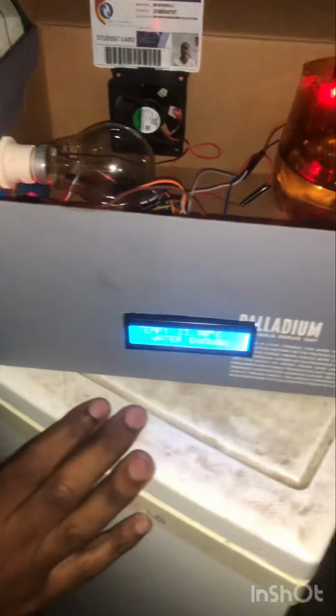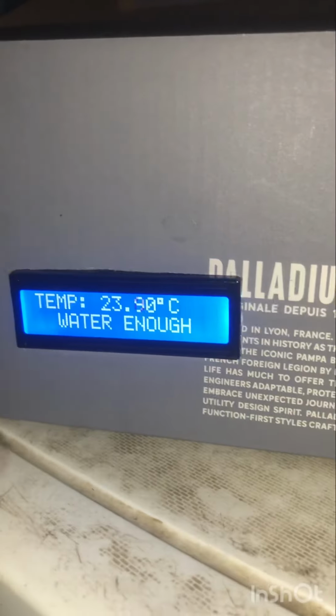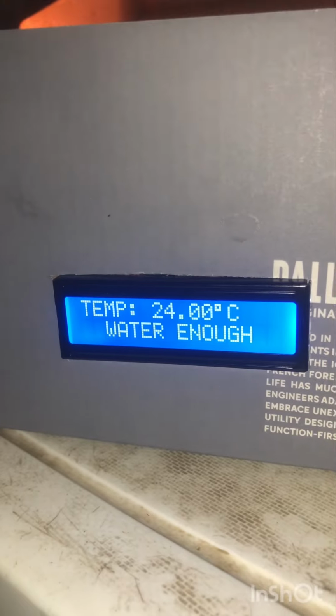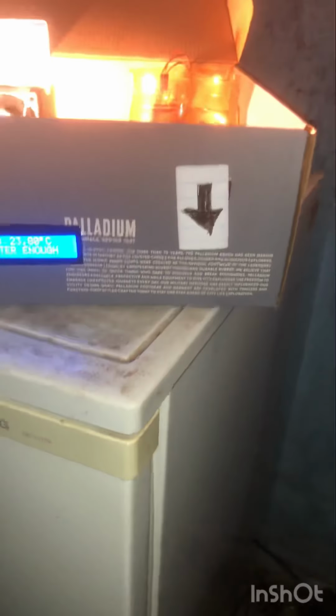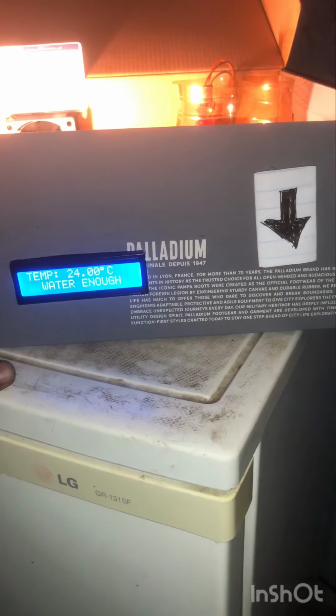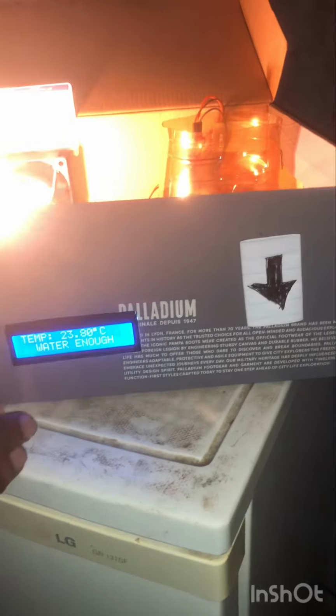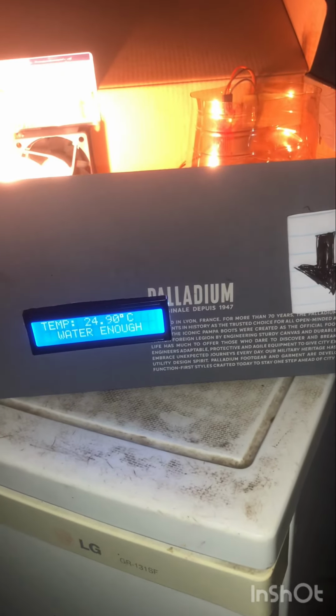Here, if you look at the temperature, you will realize that the temperature is sitting at 23.6 degrees Celsius. So it is expected that the heat source should be on, our cooling system should be off, and the window should be completely closed. And that is exactly what we are seeing at this point in time. But now that the heat source is on, you can slowly see the temperature rising, and as soon as the temperature hits 27 degrees, then it is said to be a normal or the desired temperature.